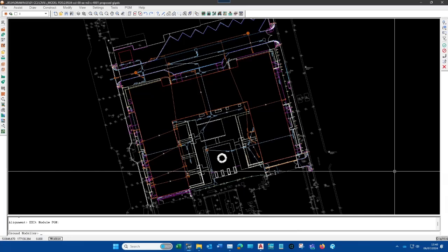So it doesn't have the vertical alignment, it's all about the horizontal alignment and ensuring that the space between the buildings, or maybe other features, maybe a water feature like a pond or a basin, that there's space to run those roads through it, and there's space to have the appropriate curves, because you have to have the curve based on the vehicle's speed. Maybe you need to make sure that that path can have a fire engine going around it. So you're doing that conceptual layout to make sure that it can work, and you don't get down into detailed design and find out everyone's house is going to burn down because you can't get a fire truck down it. That's what that is for.